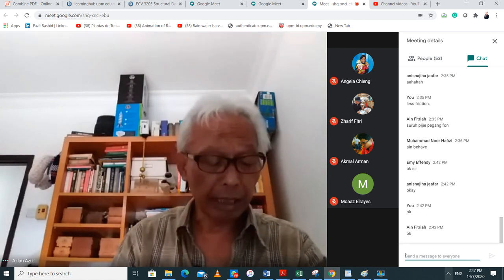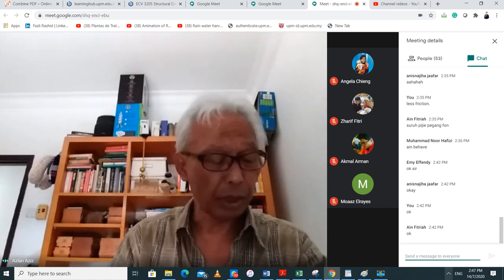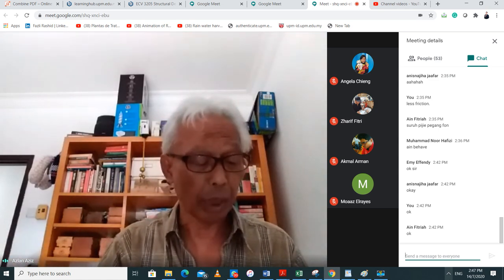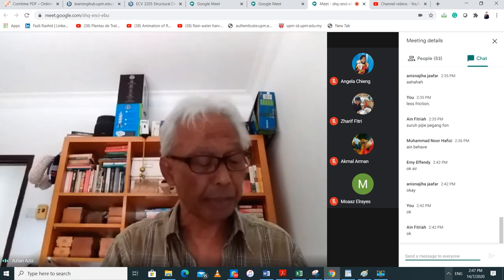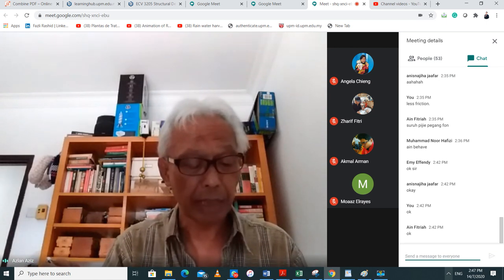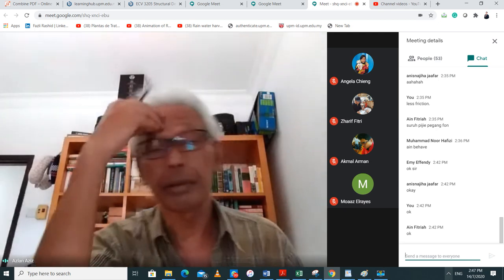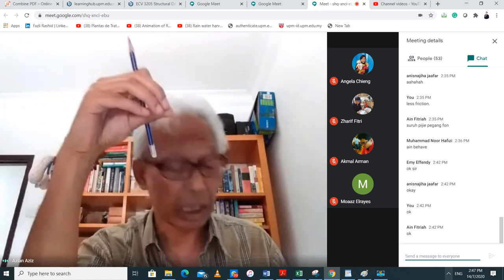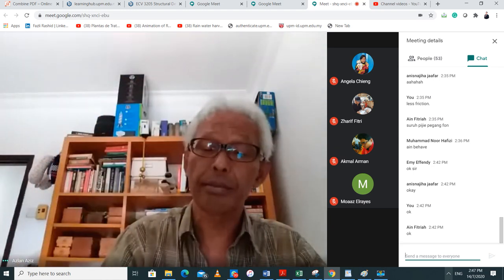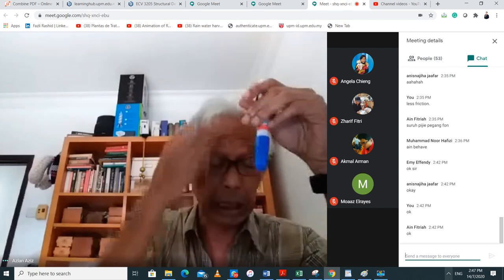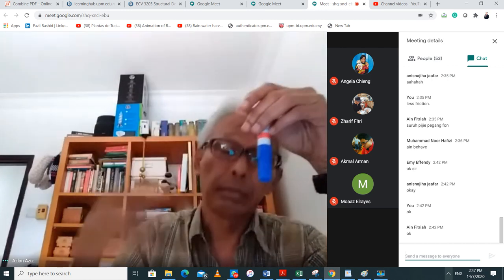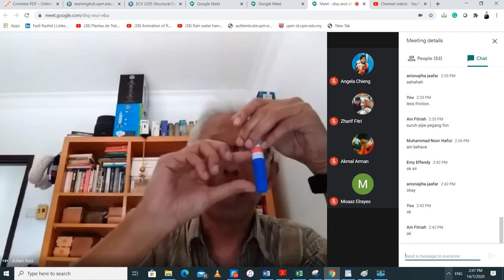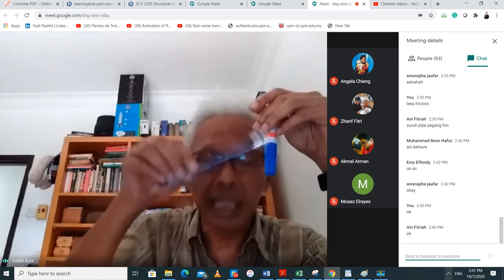Then the ultimate value of the base resistance to be used in design is 8.6. This 8.6 meganewton per meter squared is the average between 3B above and B below the base of the pile. This value is less than the damage limit of 10 meganewton per meter squared. Again, page 337 explains that in order to get the tip resistance of the pile from the penetrometer result, you need to take it 3B above and 1B below, and then you take that average value.